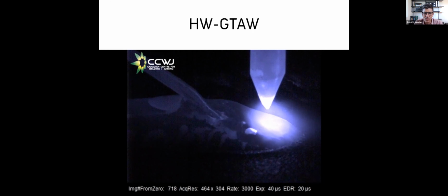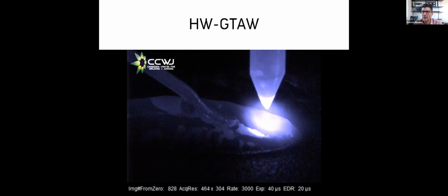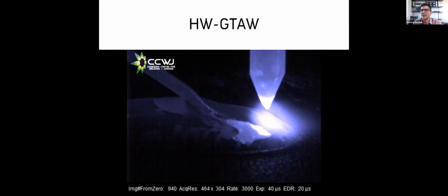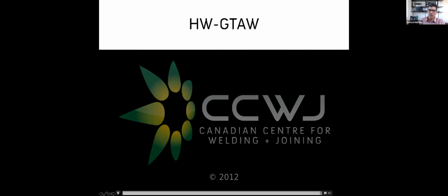Somebody suggested gas interference, but no, there is no problem with the gas. Gas has no issue. There is no wind here, nothing. Yes, somebody suggested the current being pulsed. Now we have two currents. We have a current at the tungsten electrode and a current in the wire. Which one would be pulsed? So somebody suggested there is a waveform.